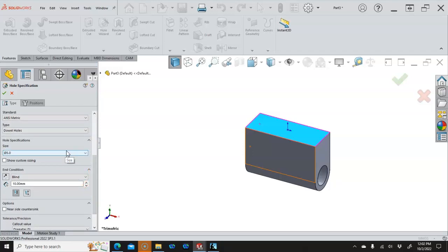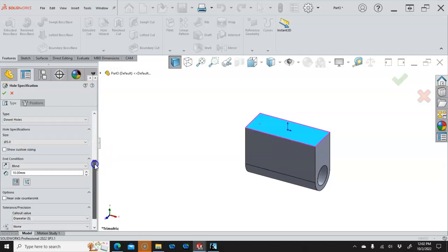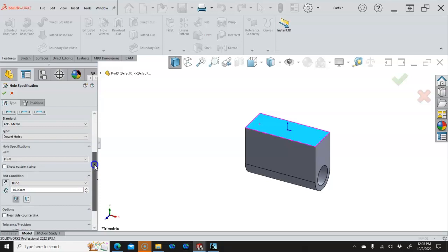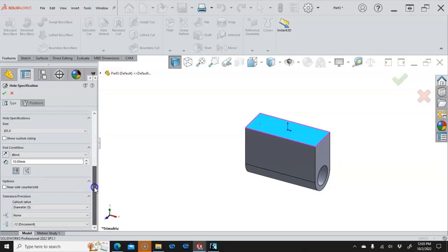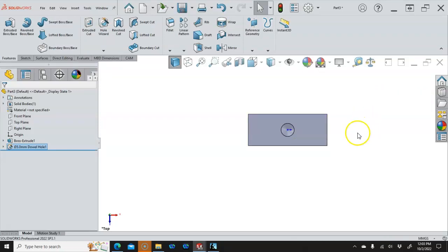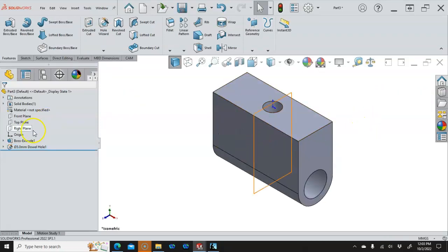So again, if we're thinking ahead to a ream, I really want to set this up to where I can make that geometry a little bit bigger, or a little bit deeper. So the 10 millimeter, and then we would need to modify the callout. So when we get to the drawing, we'll take a look at those. I'm going to go ahead and leave it at 10 millimeter, and we'll add a note to ream to 5 millimeter and have the extra to make sure that there's clearance for the geometry. So this then is our slider.